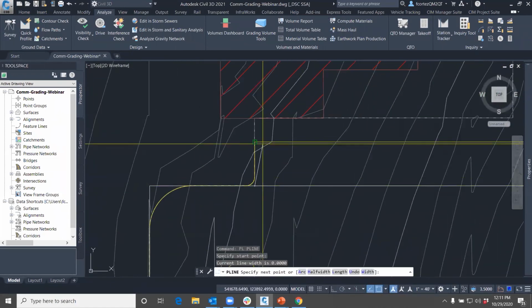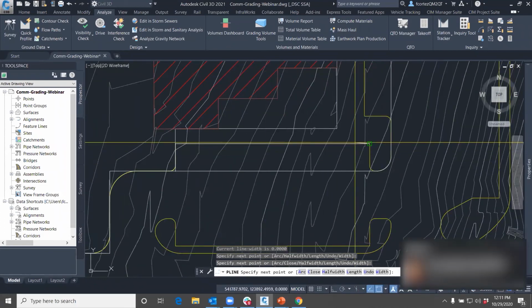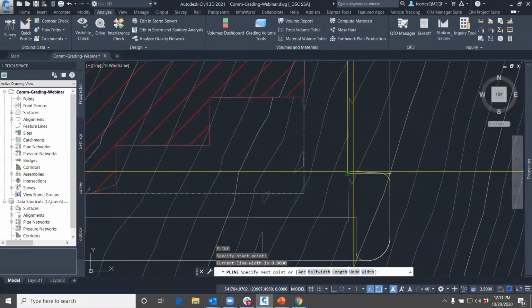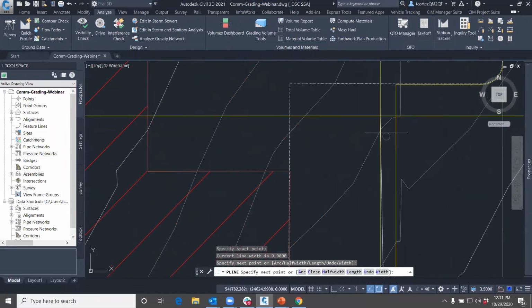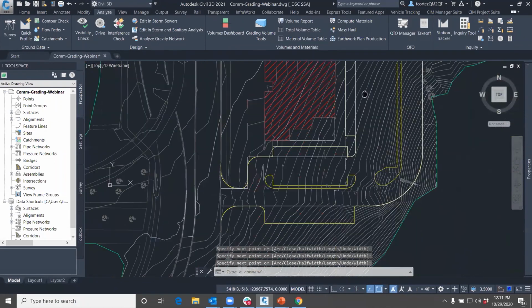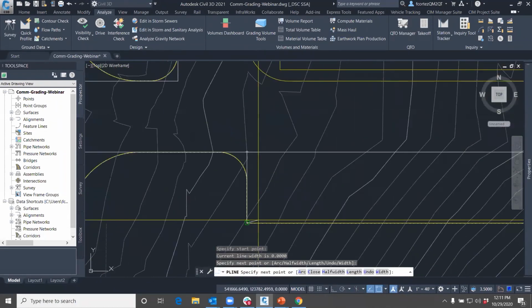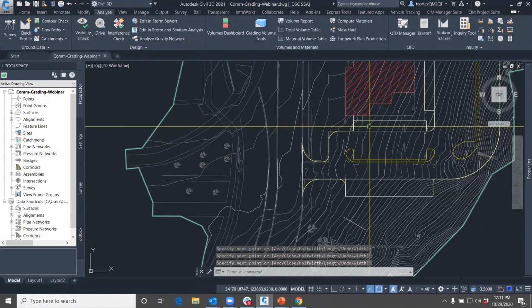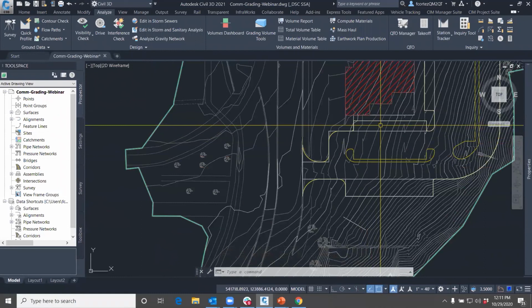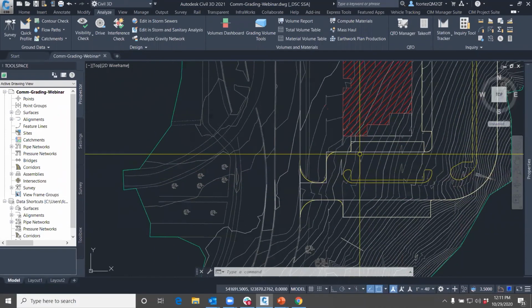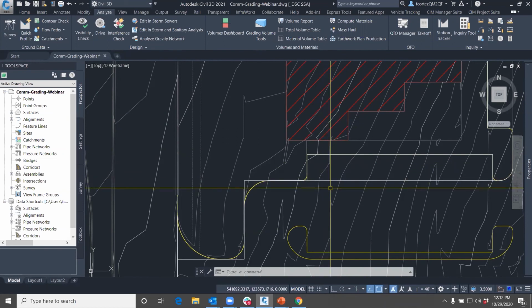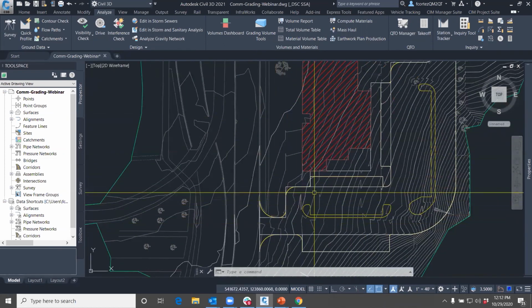So now what we want to do is break out the parking areas. We'll just go to all of our endpoints. And down here, we'll do the same. Like I was saying initially, we blocked off the grading to be able to happen in our parking area. That's going to be separate from our main drives. In a typical situation, you might want this to come up at 2% and push all the drainage towards your parking area, which in this case, if we look at the natural contours, really wants to come down to this corner naturally.